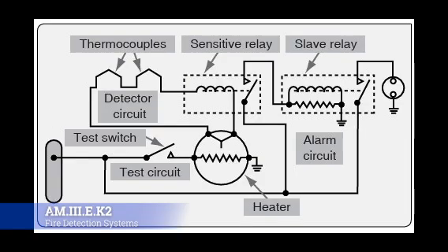Okay, probably a little bit more common you'll find is a thermocouple on an engine primarily, but also other parts of the aircraft as well. These work on an entirely different principle than the thermal switch system. So a thermocouple depends on the rate of temperature rise, and it doesn't give you a warning when the engine slowly overheats. So it can just get slowly hotter and hotter, and you can watch the EGT just climb, climb, climb, and it won't give you a fire alarm. It only throws the alarm whenever there's a sudden jump in temperature.